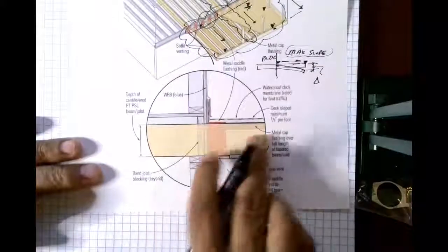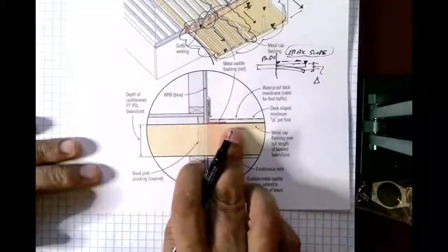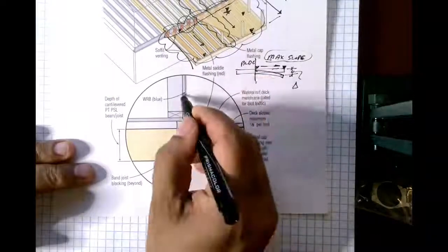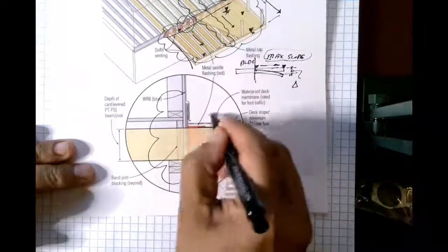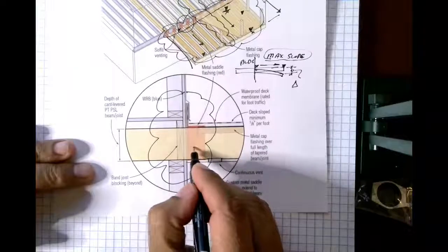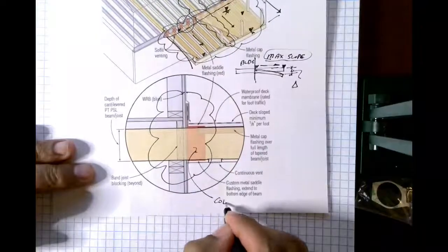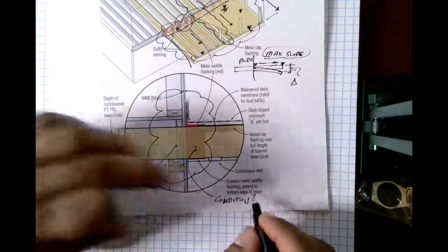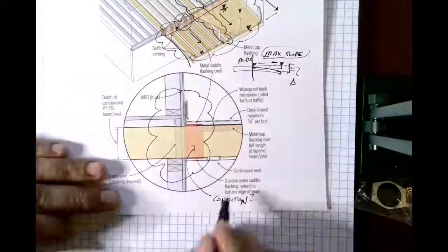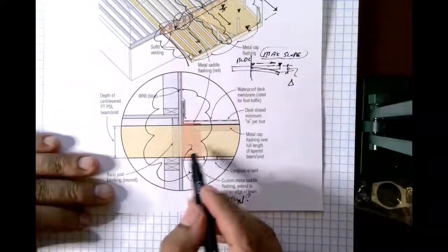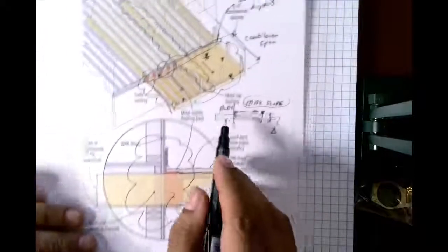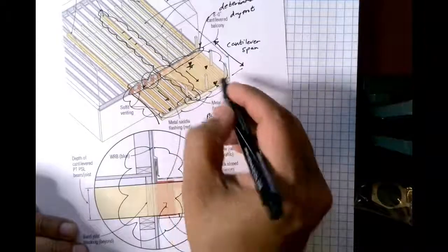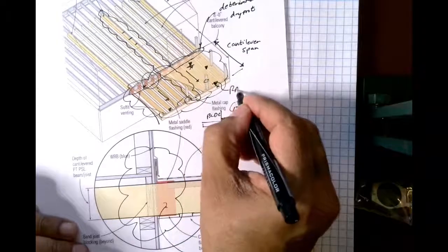Then we come back and we look at this connection, and if we find that it exceeds the maximum slope, then we have to expose this connection and see what's the condition of the wood. Is it in good condition? Is it dry rotted? What's the condition of the wood out on the edge here? And then, of course, we also have to look at these railings.